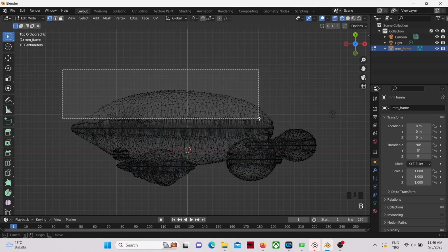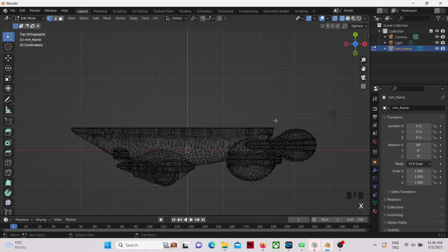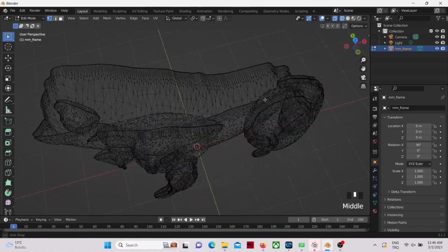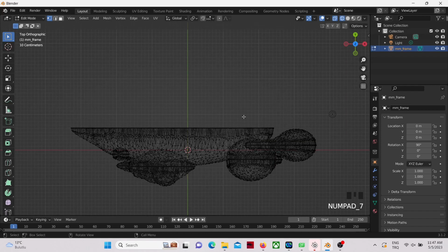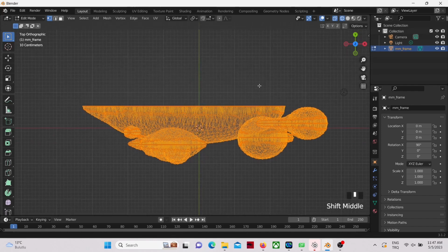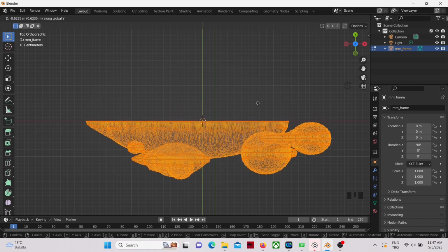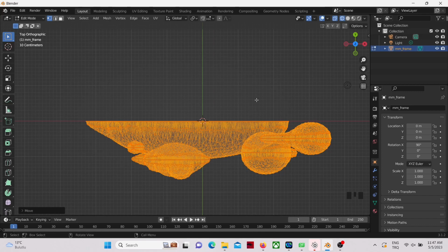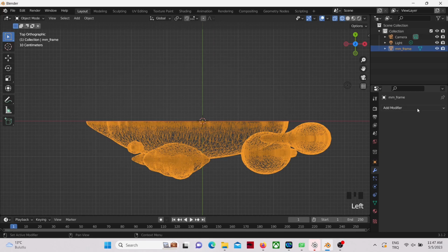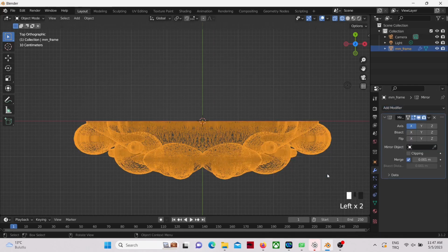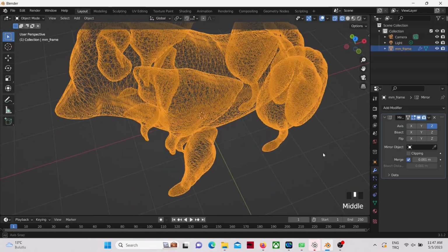So in order to make modifications, we will switch from object mode to editing mode, and in editing mode we will delete one half of our 3D model, and then we will select every vertex and we will basically grab it and drift it so that it lies on the x-axis. Okay, and then we will now add a mirror modifier so that we don't need to deal with every detail for both sides of the wolf. Okay, now we have a symmetrical wolf-like thing.